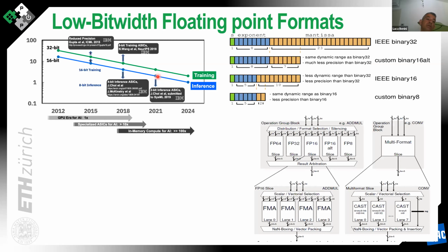So what we integrated in Ariane and recently released open source also independently is called the Trans-Precision Floating Point Unit. This is a floating point unit that you can use to run either 64-bit floating point calculations, or 32-bit floating point calculations in SIMD2 mode, or 16-bit floating point computation, either a normal standard floating point or extended range floating point, also called brain float, and finally even 8-bit floating point with SIMD8 capability, whilst we have SIMD4 for 16-bit.